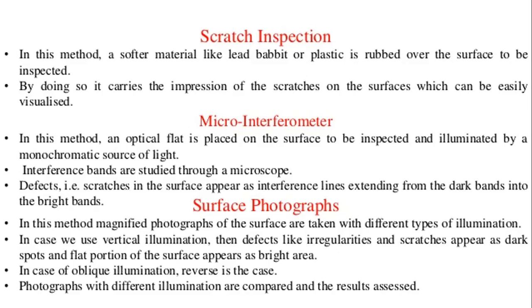Next one is the microinterferometer. In this method, an optical flat is placed on the surface to be tested and it is illuminated by a monochromatic source of light.